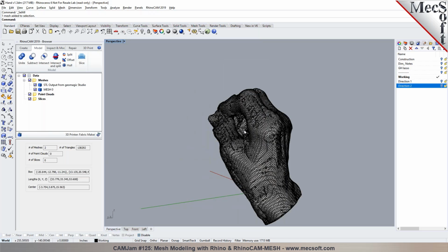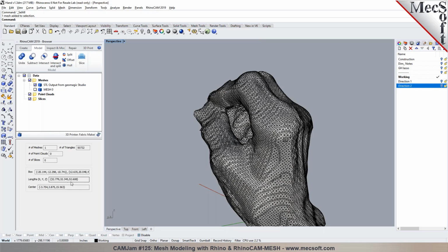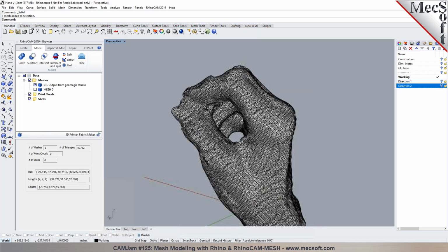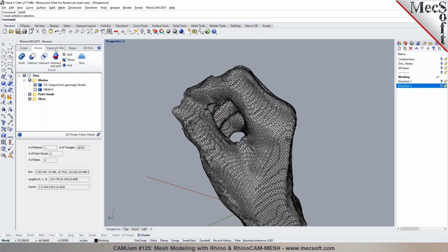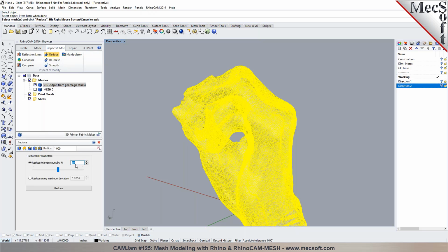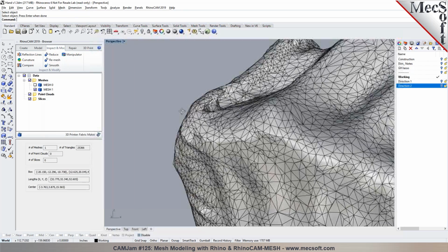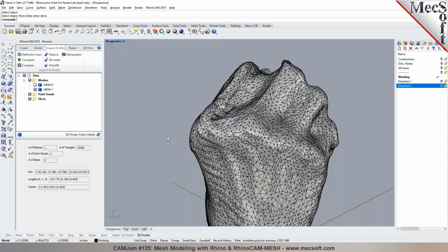Okay. All right. So if I check the size here, it's 32. Yeah, it's a fairly large mesh in here, right? So I probably used a really small value for the. You did. Yeah. So I can go back and remesh it with a much larger value. So reduce the triangle count. So I can go ahead and say reduce it by 50% of the amount. So basically it reduces. You can see now you have your triangles in here. Oh, yeah.